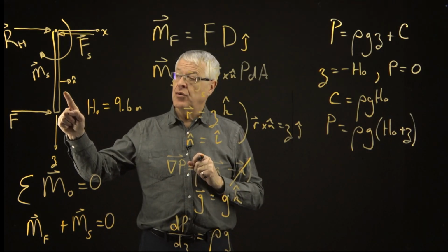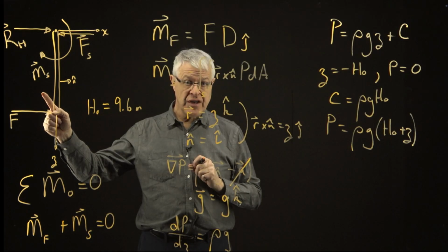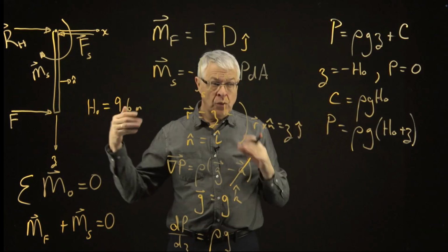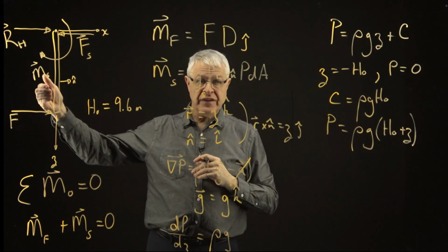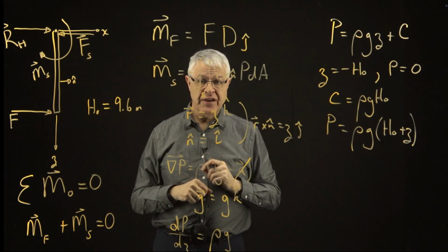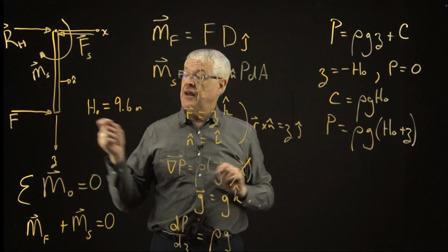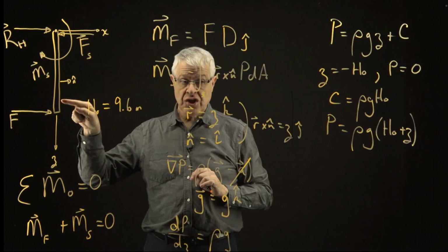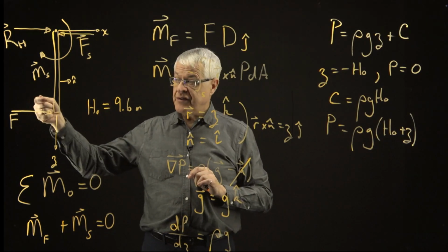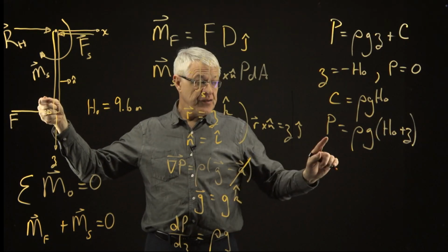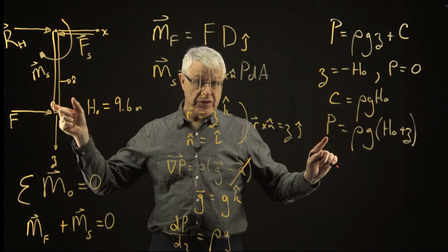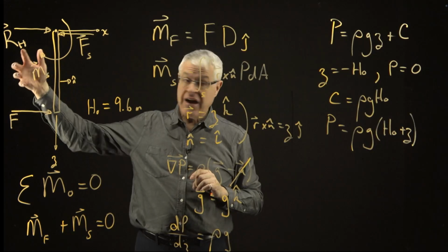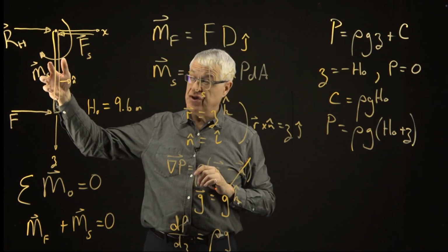All right? Well, realize we have atmospheric pressure on this side. So by using a gauge pressure here, setting this to 0, we're basically automatically removing the effect of the atmosphere pushing on the other side. You could think of this pressure as an equation for the pressure difference on the two sides. So we have a very large pressure on this side, but there is still pressure pushing on this side. So the gauge pressure is the difference between those. So this step right here is how we account for the fact there's actually air pushing on the other side.